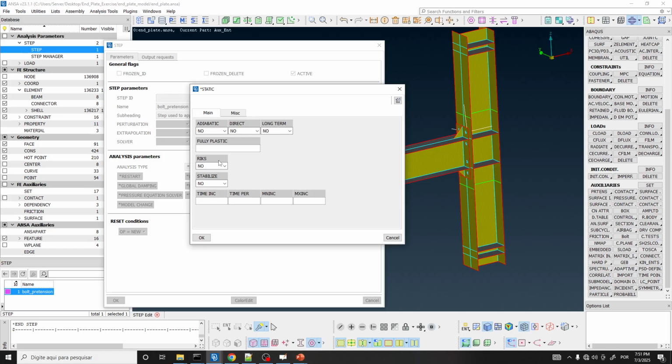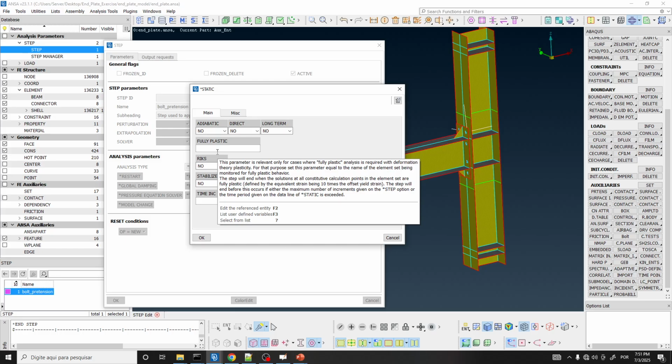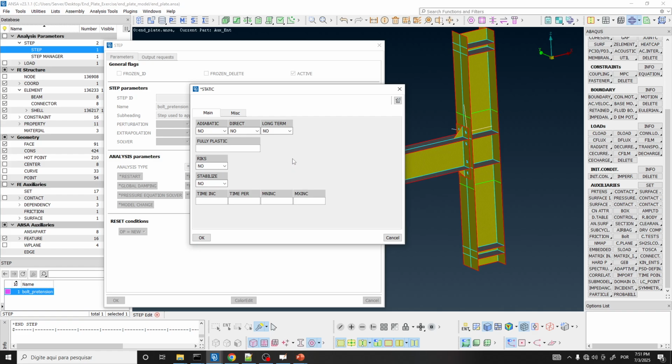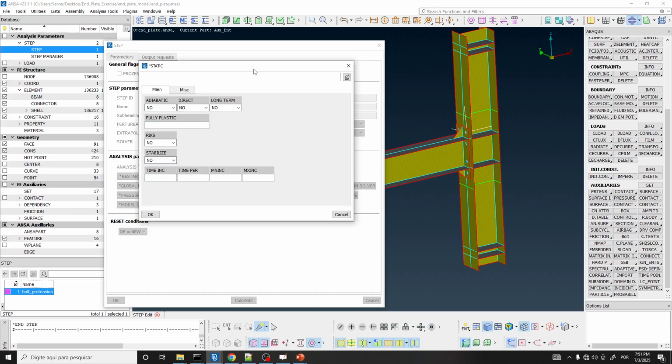We know that the Newton-Raphson method is the one that is used to update the stiffness matrix inside each increment that we have in the nonlinear analysis, right? We have iterations of equilibrium inside one specific increment, and for each iteration of equilibrium, we need to update the stiffness matrix. Actually, the Newton-Raphson method is used to check if the model has converged or not. So it calculates the residual forces and moments, and if this is above a limit that we define or the software defines, then it's going to perform one additional iteration of equilibrium. So the stiffness needs to be updated. This is something that we have learned in details.